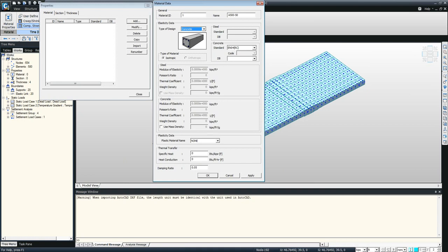There is a question from Russell Jack. It's a very interesting question. The question is, when analyzing a composite bridge, one of the techniques is to model the negative moments as steel only and the positive moments as composite, since the area with the highest moment of inertia will attract the greatest moment. How does Midas do it? So let me reframe this question.